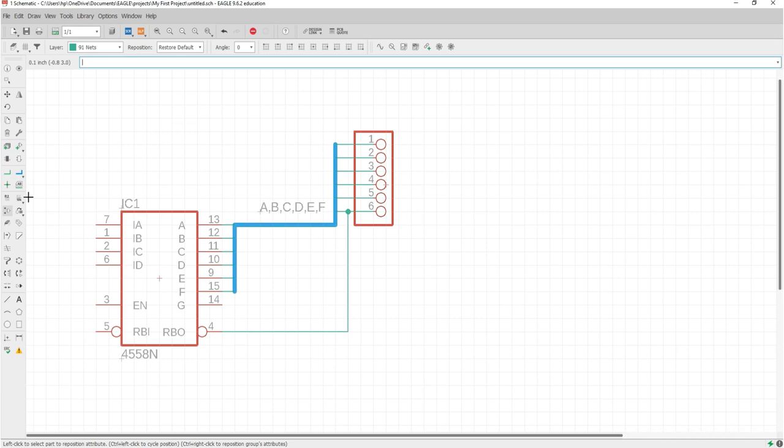The first is a drop-down allowing you to target what you'd like to do or what attribute you'd like your changes to apply to. Smash Only option will unlock the component text and you can move this around as you always have. Selecting name, value, or name and value enables you to specify predefined positions for the component text. Then, click on your parts to align the text automatically.